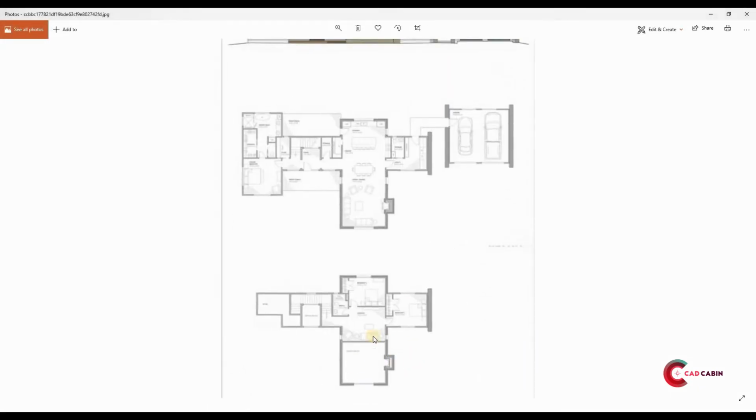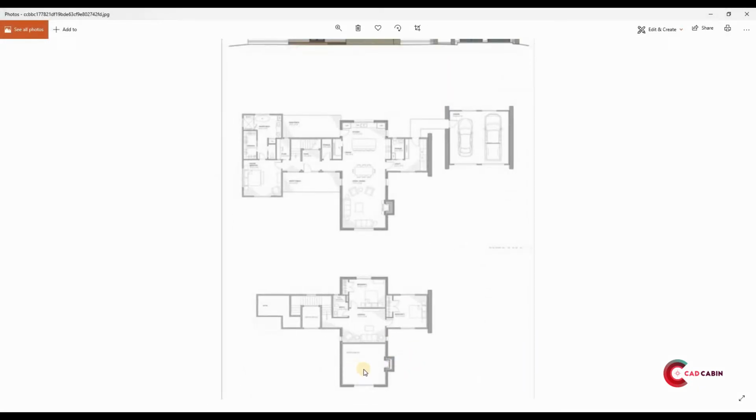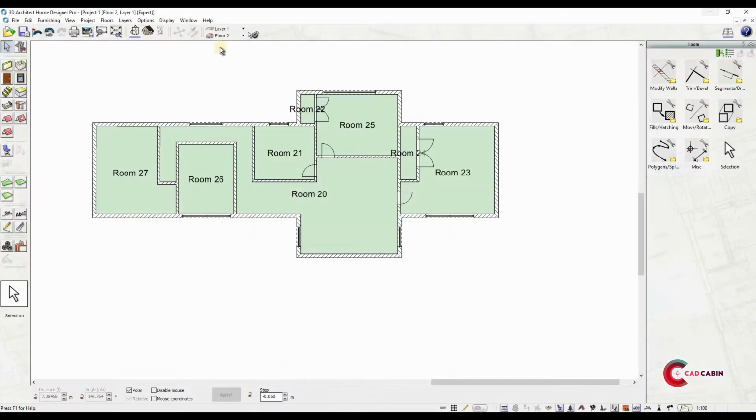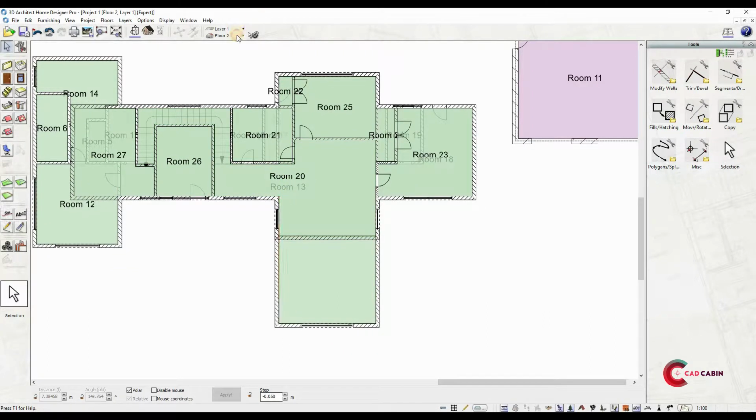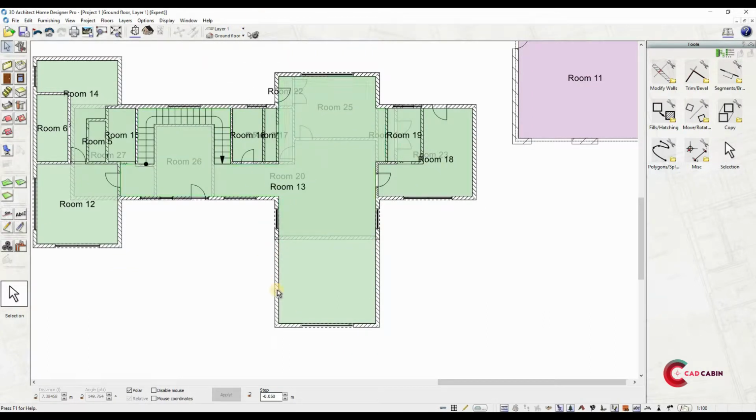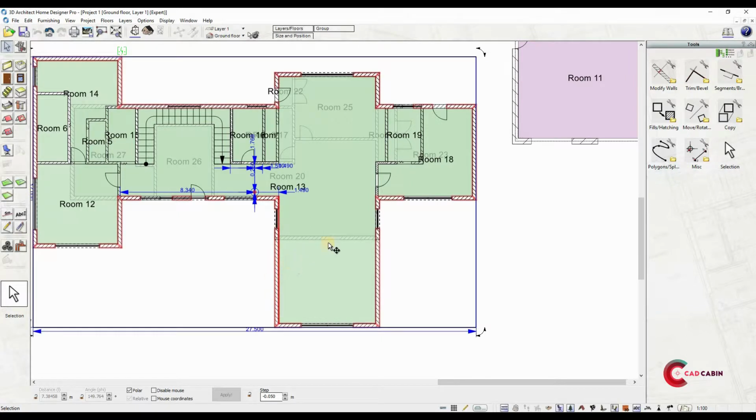In the house plan that we have, there is a 2-story high ceiling area above the living room. To do this, first we have to select all floors visible. This is to give reference on where the high ceiling area is. After that, select ground floor as your active floor. We will be editing the current exterior walls.